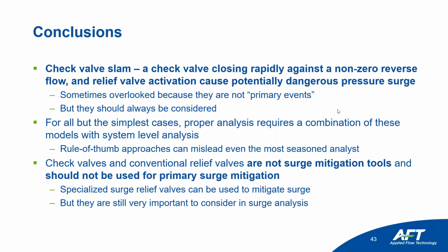A second question here I see is about the check valve values. We'll read this because it's a great question. Due to the lack of manufacturer's data, we only use basically estimated data from a table. So for example, a swing check valve might say the reverse closure value is -2 feet per second. A silent check valve is -0.3 feet per second. And the question here, a really key one, is how far is the use of these values from the possible reality of check valve behavior?